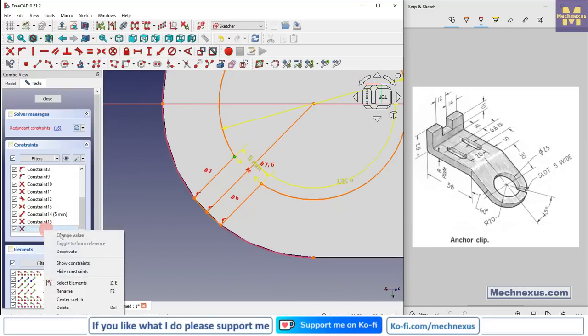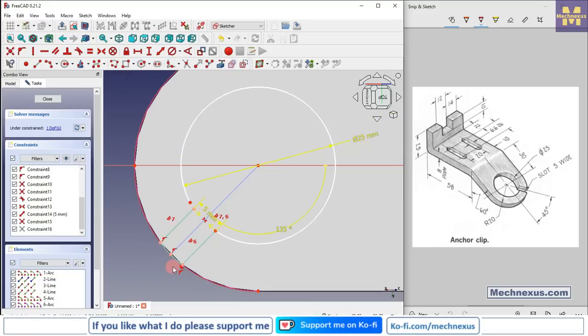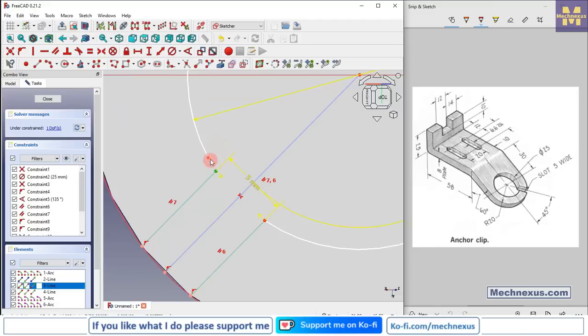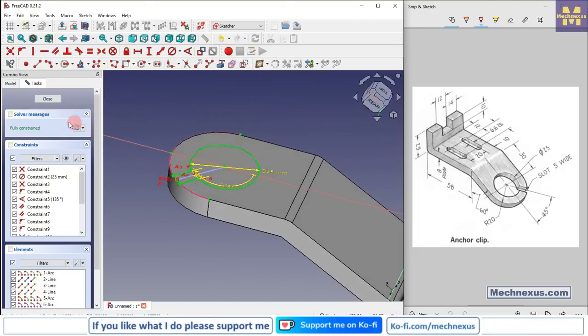and let's deactivate it. And now let's find out what is unconstrained. So we will delete it. We will select this and this and say merge. Select trim and select 3-point arc, and make it equal. So we have a fully constrained sketch.